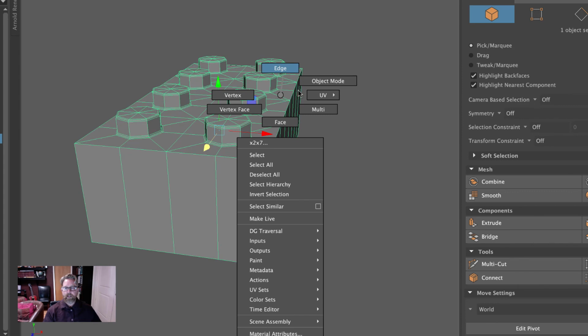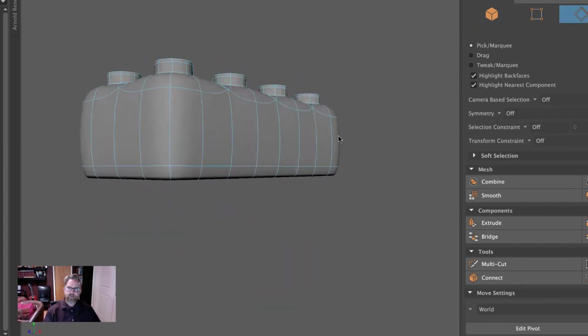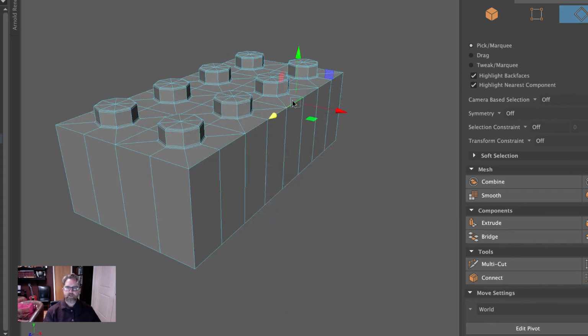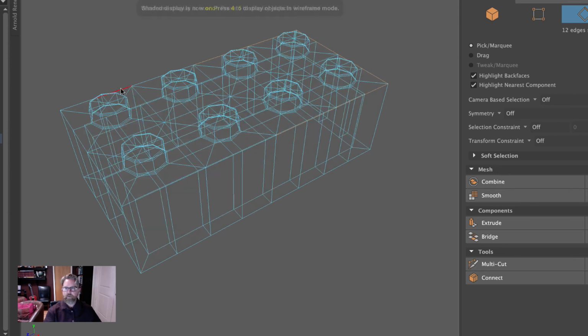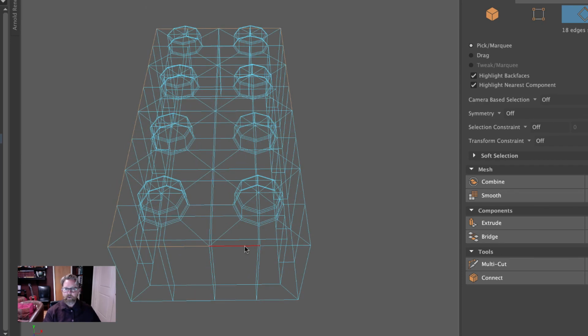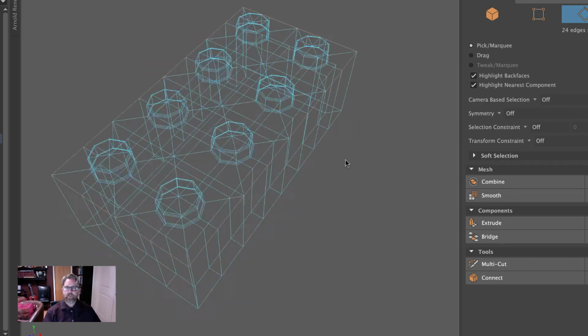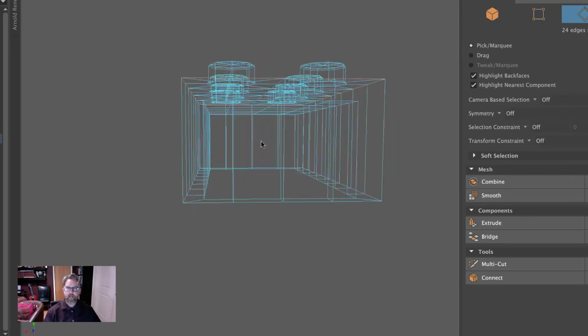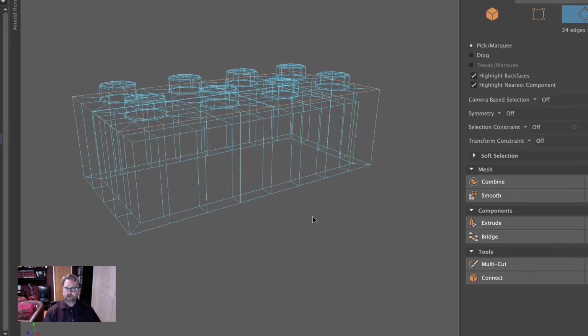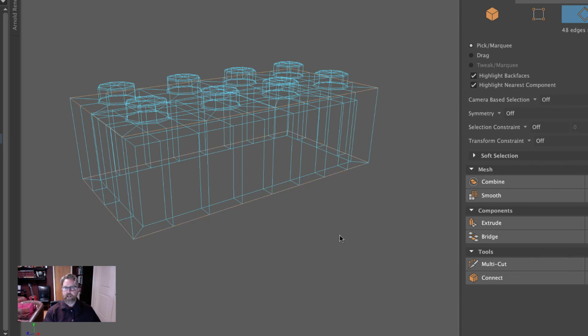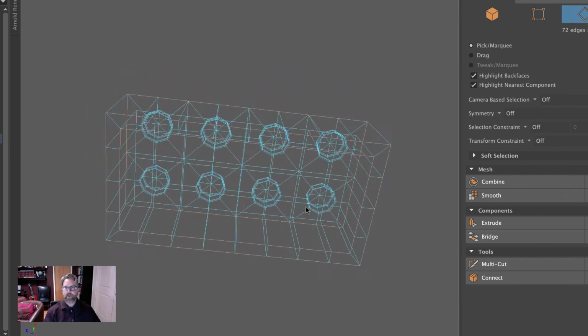Now, we'll go back and, right, we can't subdivide this one until we've beveled it. So we'll double click, and maybe the 4 mode is easier to see. Double click, and we'll dolly around, get a better view. So I've got the top rectangle only. I didn't make any bad selections. If you had, control select them. We're going to skip the corners for now. Let's just do the rectangles first. We'll double click. We got all the way around. Shift double click that interior bottom. You get all the way around at once.